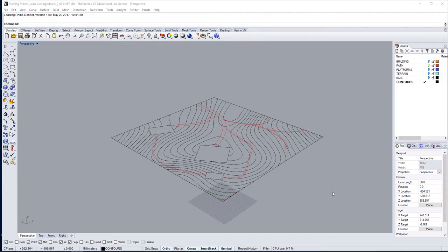The focus of this video will be on how we can recreate our contour model in Rhino using only 2D planar elements, now that we have generated contour lines for cutting. This will involve modelling the material thickness we wish to use and begin to assemble the model in Rhino. Firstly, as a reference for when it comes to the physical assembly, but also to ensure we create an accurate support base.